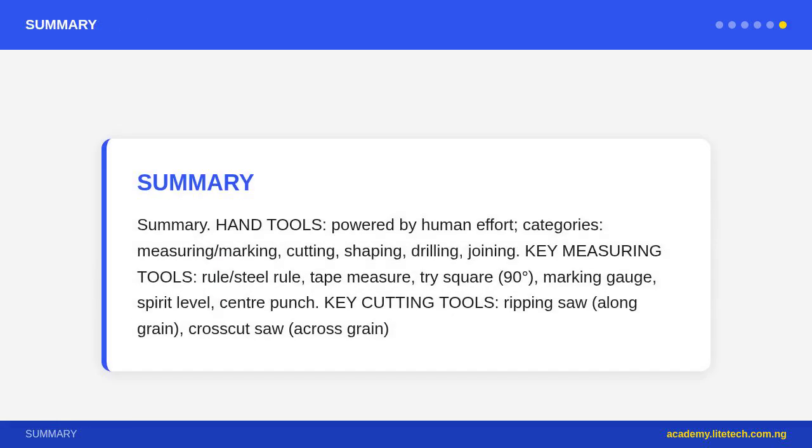Mistake 3. Tapping a wood chisel with a metal claw hammer. A metal hammer on a wooden chisel handle will split and mushroom the handle in a short time. Use a mallet, wooden or rubber head, for chisels. The claw hammer is for nails only.